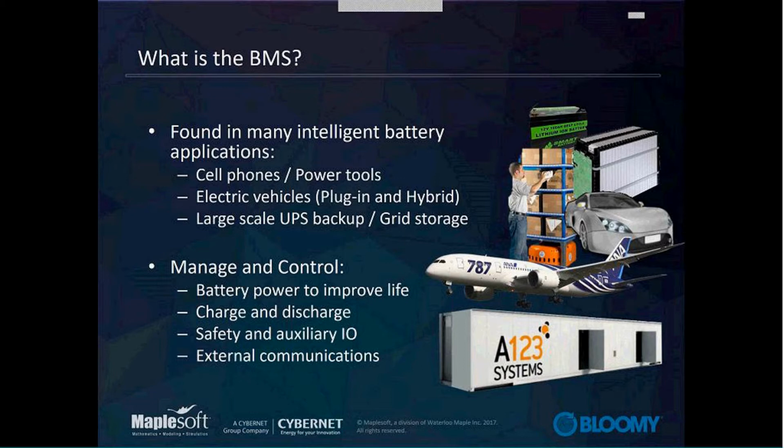The primary purpose with advanced lithium batteries is to manage and control those battery cells, to maximize the power of the battery, to improve its life, to control the charge and discharge functionality of that battery pack, to ensure safety and auxiliary I/O, to make sure that the product operates in a safe and usable state, and finally external communication so that it can be a subsystem within a greater system, such as an automobile or an aircraft.